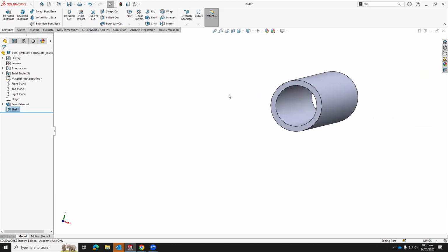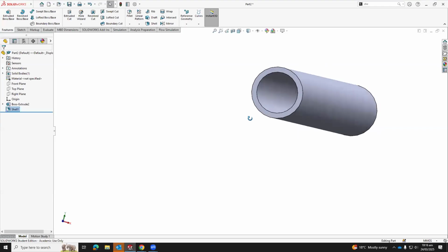Now, if you learned from fluid mechanics, to study anything, I need to have what we call a watertight geometry. It means SolidWorks needs to understand where the boundaries of the fluid are, where it's coming in, where it's leaving. It's kind of like a closed system, treating it for internal flows. So I will show you how to do that when we start with the CFD, because this is just an open pipe or tube, but we need to go through it. As soon as I finish, I need to save. Again, FEA and CFD files create big data. And CFD creates even bigger data than the FEA.